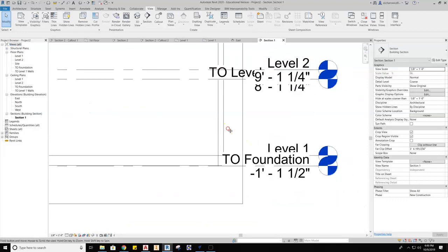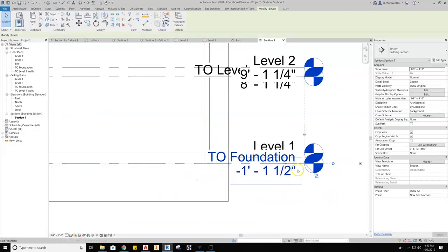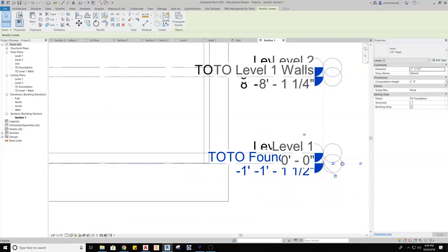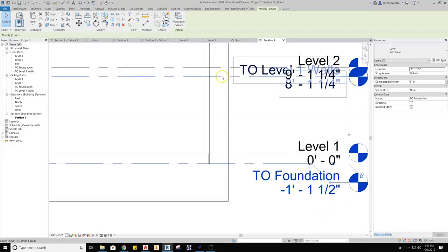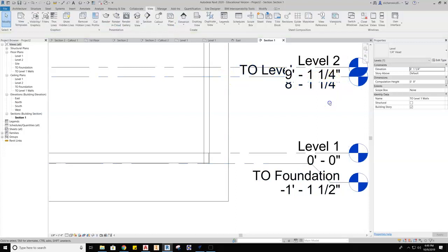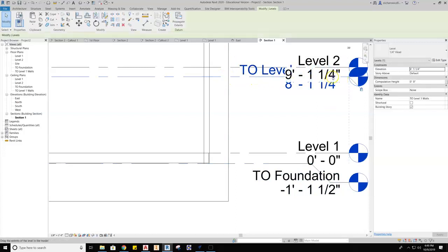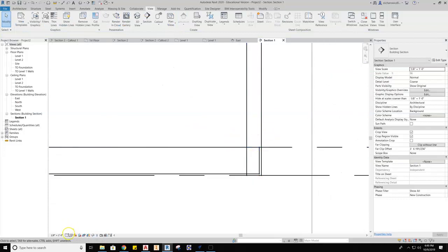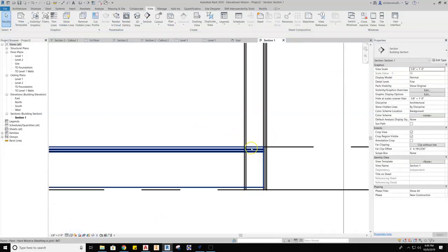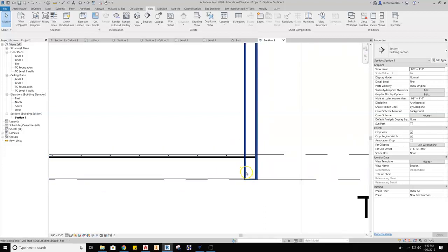So as I'm taking a look at this, first thing again, let's go ahead and maneuver our levels out of the way. Drop our elbows so we can see what's happening. Always have a nice working drawing here. And as I'm looking at this, I need to do my detail level also to set that up. And you can see how things are working out here. This wall is running through the floor system. What we need to do is we need to join these two together.